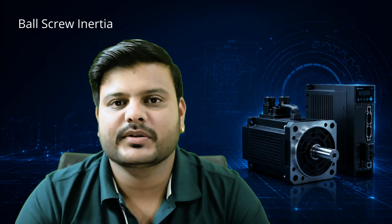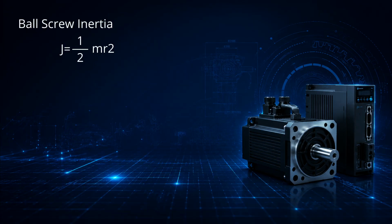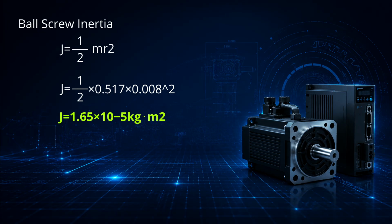Now the next step is to calculate the ball screw inertia. To calculate ball screw inertia, we know the formula J is equal to 1 half m r square. Substitute the values in the formula, so we get J is equal to 1 by 2 multiplied by 0.517 multiplied by 0.008 square. So we get J is equal to 1.65 multiplied by 10 raised to minus 5 kg meter square. And this is the inertia of the rotating ball screw alone.